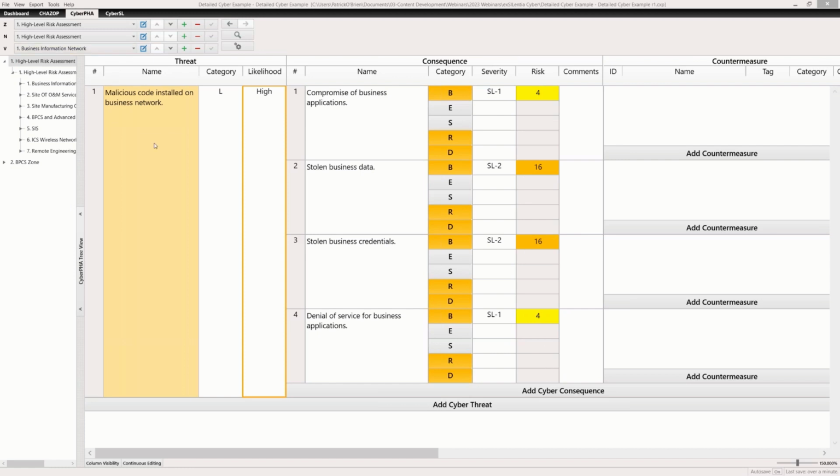And so this can be used to support both of the, I'll say, common initial risk assessment methods that I've seen. So either an asset-based approach where you start with the network architecture and look at how critical each of those devices could be, as well as a PHA-driven approach where you're doing a security PHA review to identify whether or not a consequence could be caused by a cyber event.